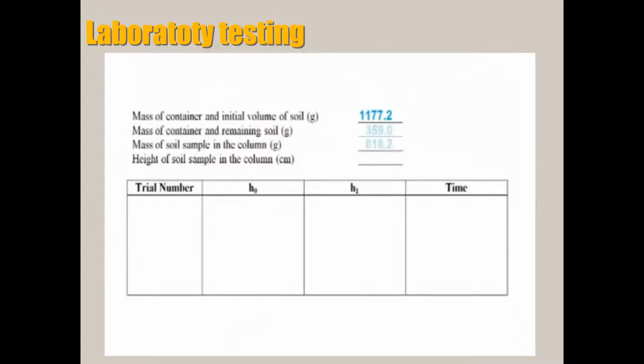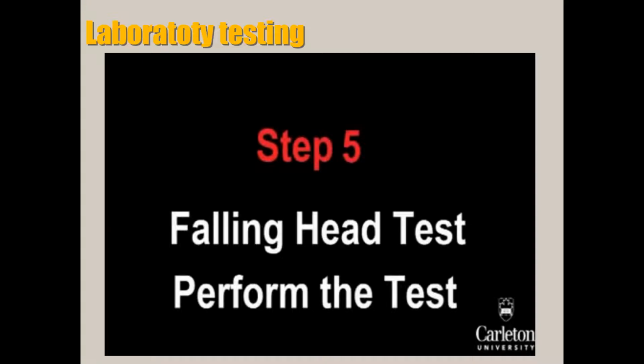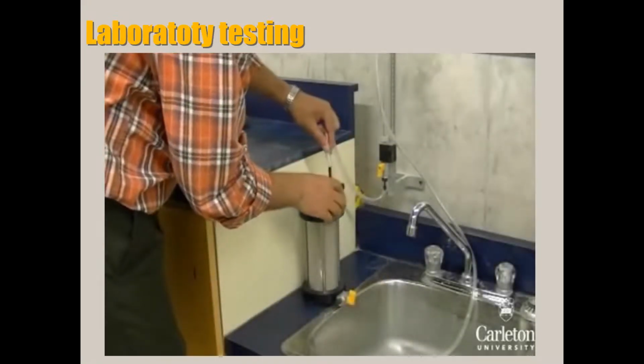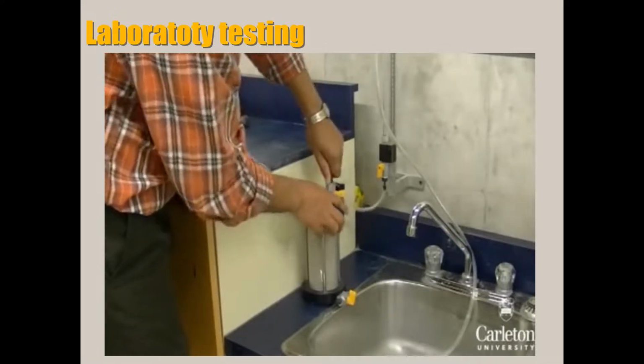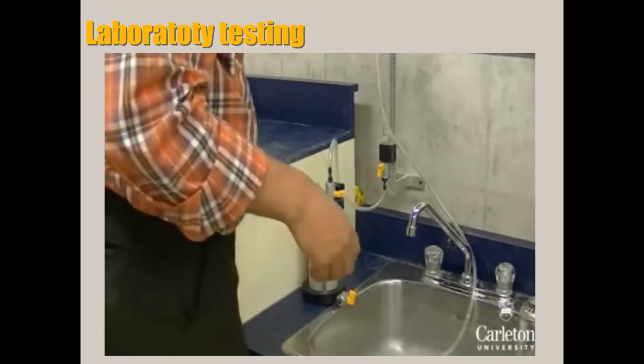Finally, record the mass of the soil container plus the unused soil. The cylinder for the falling head test consists of just one line connected to the test cylinder. Connect the line to the cylinder. Before we can start the test, we must saturate the soil with water.